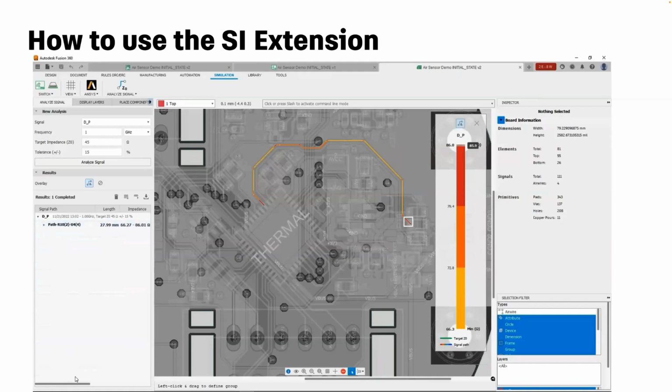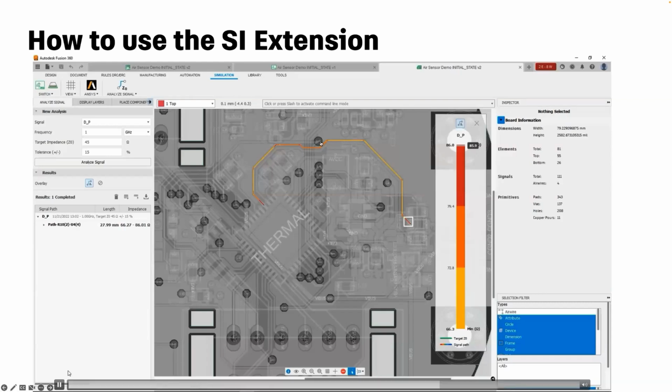So if you notice near the ends, like I'm showing here, there's areas where we have big deviations, and it's because the separation is changing between the differential pairs. But we also have areas where the polygon has broken. And because of that, there's no polygon filled in those areas, and that causes the impedance to change as well. So if you look in this trace on the top northern area of it, you're going to see that it's orange, and it's because of that.